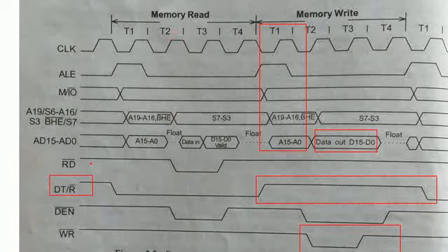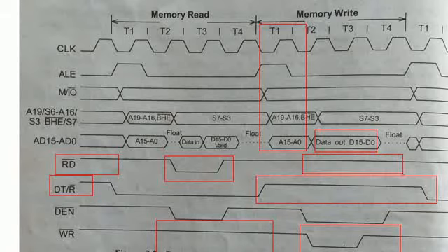Again, remember that when the read signal is active low, while performing the read operation, the write signal is in the active high status. And when you are performing the write operation, then the read signal is in the active high mode. It is only for realizing exactly how the signals change their status depending on the type of the operation, but nothing to do with this in the exam.